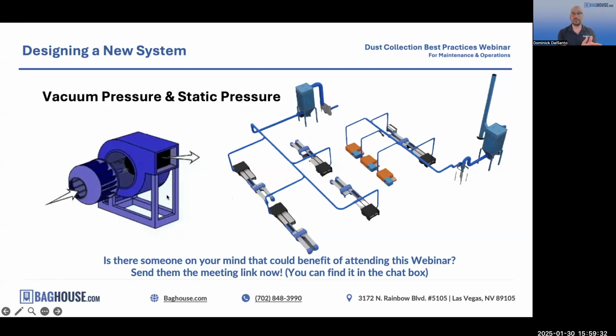So if you have one short little run of duct with one pickup hood, you probably need just a little bit of static pressure on the fan, or vacuum pressure, sorry. You need just a little bit of vacuum pressure to overcome that resistance. Whereas if you have a big spidery system with lots of little branches or really long runs of duct, you need to make the fan have a lot of suction on it to overcome all of that.